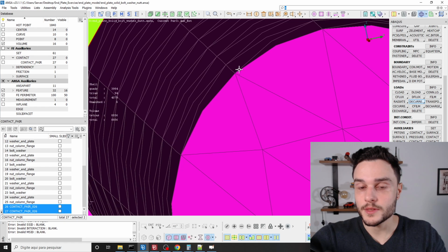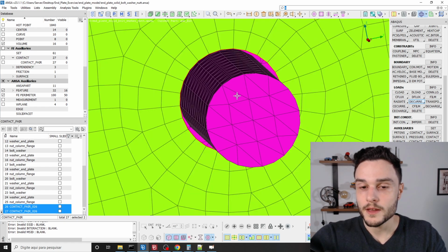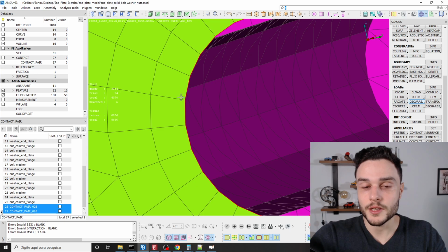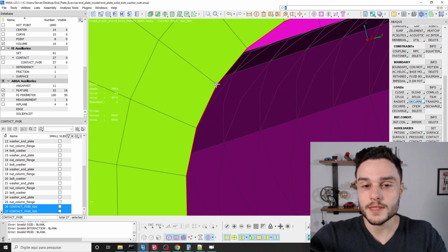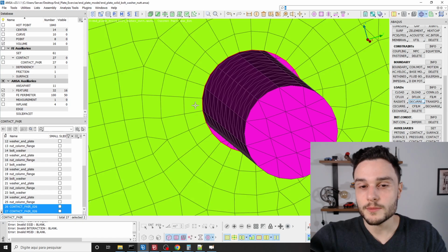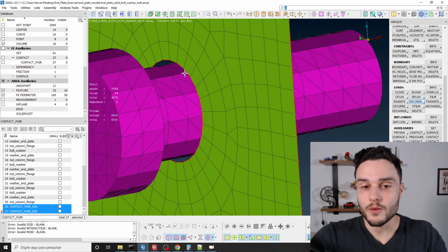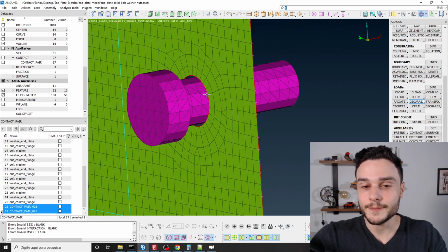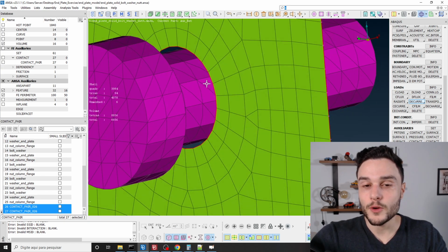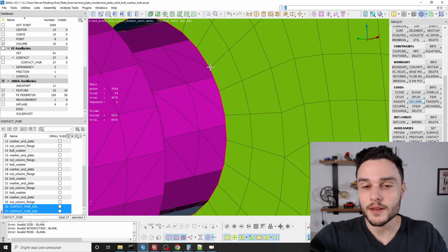And then we have many segments of curves, which is representing well a circle, right? But the problem is with the shell elements, because you see that the sides of the shell elements are straight lines, right? And this brings some difficulty in the convergence of this contact, and also the contact pressure distribution is not so correct when we have this kind of discretization. For node to surface contact formulation, the solver analyzes if the node, the slave nodes are penetrating on the master surface.